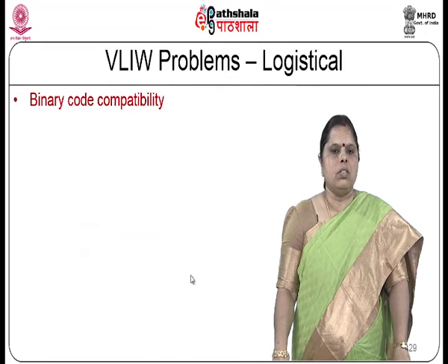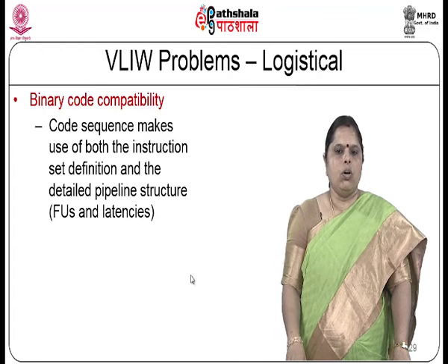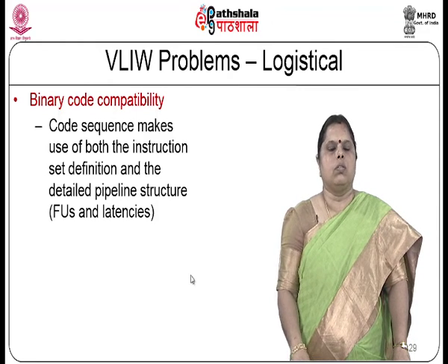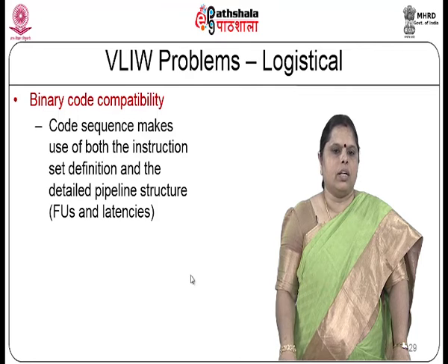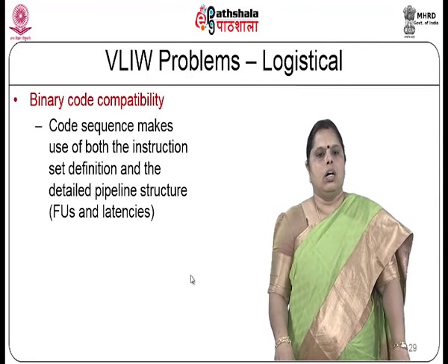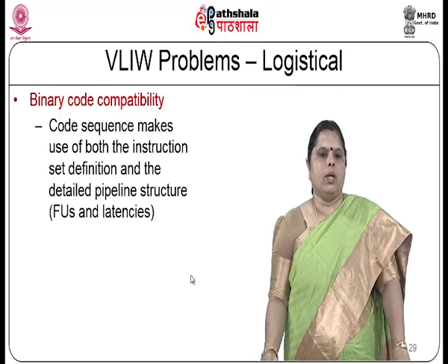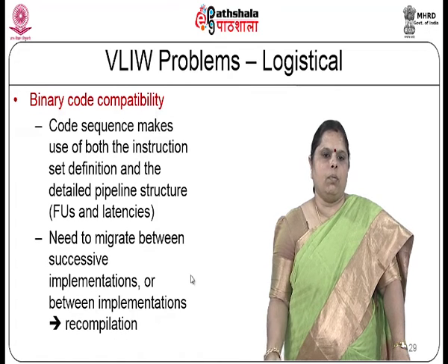The other logistical problem that you have is binary code compatibility. Because the instruction opcode is generated based on the instruction set architecture as well as the latency of the functional units and all that, it is not possible to have binary code compatibility. So, that is one drawback of VLIW processors.